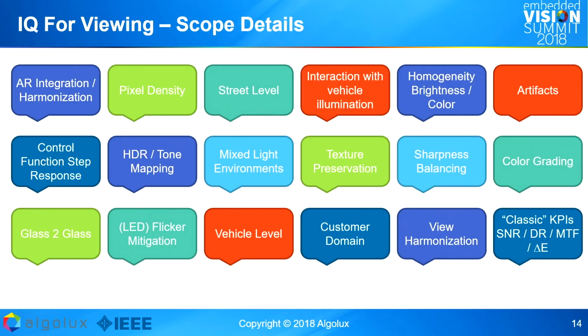And here the standard really borrows a lot of the measurement techniques that had been previously used in other domains, such as cell phone imaging. There's CPIQ, which has a number of sharpness, texture metrics, color metrics. But we also add additional metrics and use case specific problems such as LED flicker, tone mapping specifically to automotive situations is an important topic.